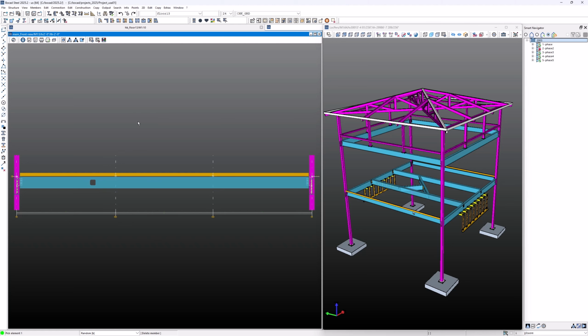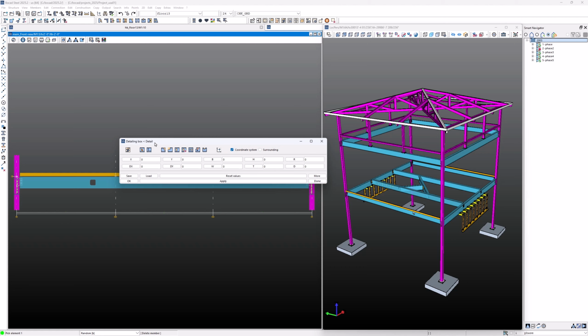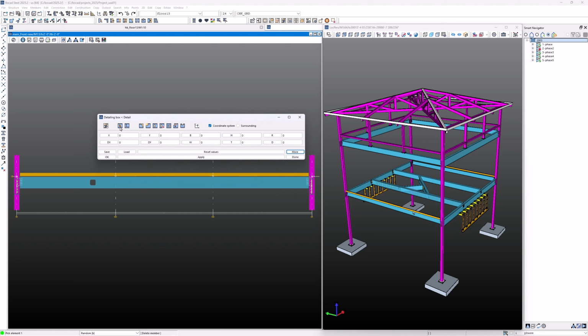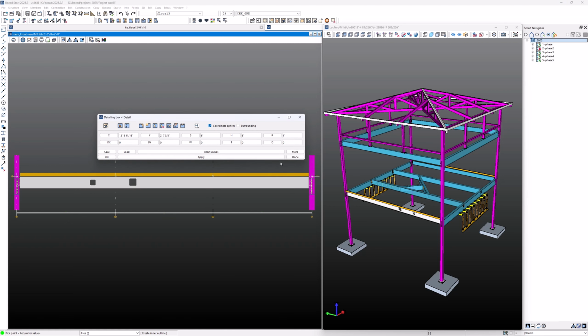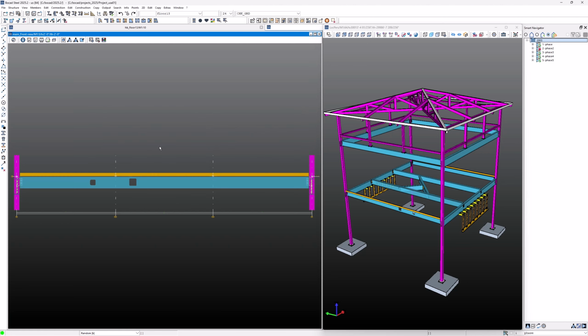What would be another one? Another one would be to go through the detailing box. So I will have to pick what I want to edit, give it a certain width, let's say about 6 inches, 6 inches high, 1 inch radius, and then we say I want an internal contour, place it over here, and then I have a hole with rounding.